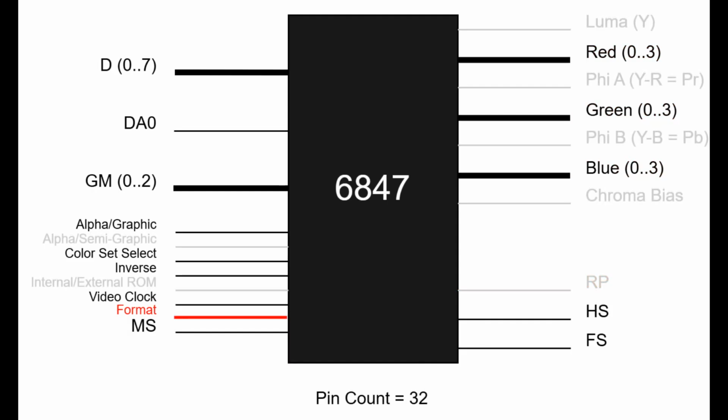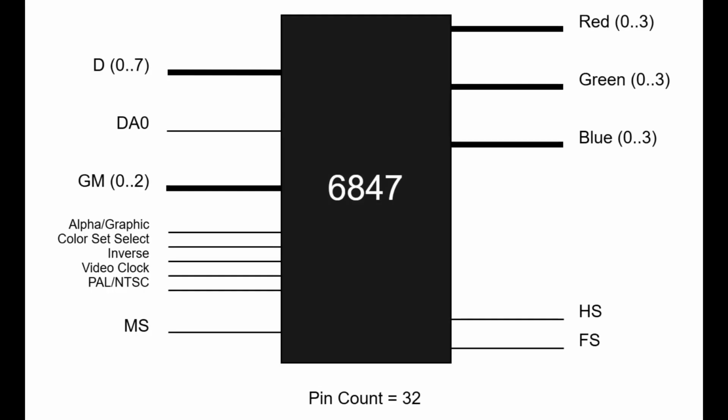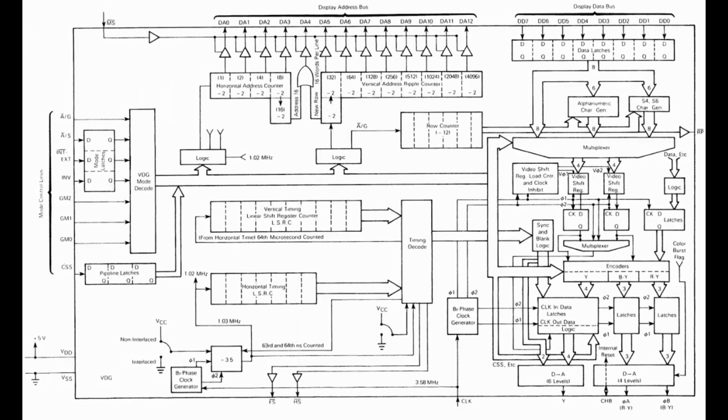One extra detail is that I want to be able to switch between NTSC and PAL frame timing, so I need an additional signal on input to control which is in use. The tally then is that I lose 11 out of 12 address pins and 3 of the 10 control signals. On the other hand, I add in the output format, and instead of just 4 pins for video, I have 12. The final score then is, instead of 38 pins on the original chip, I only need 32 pins in my implementation. Enough hardware, I promised implementation details.